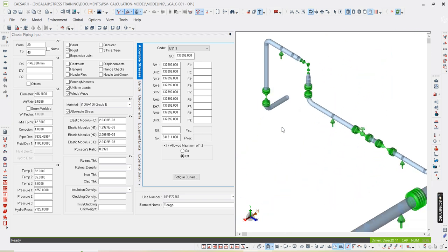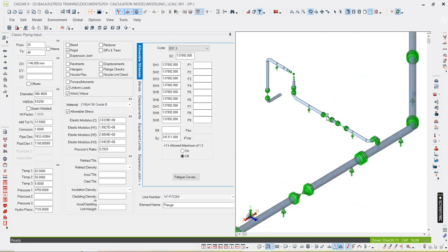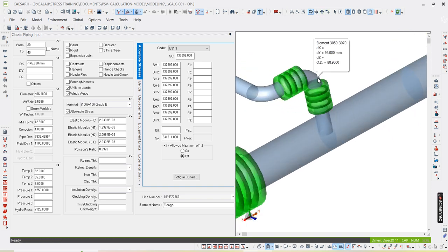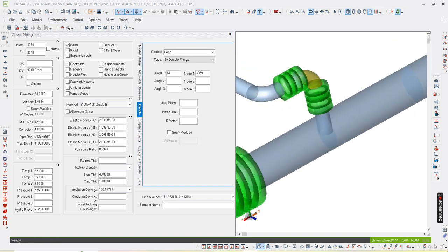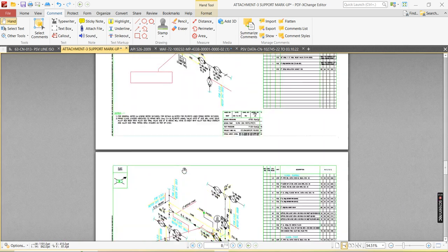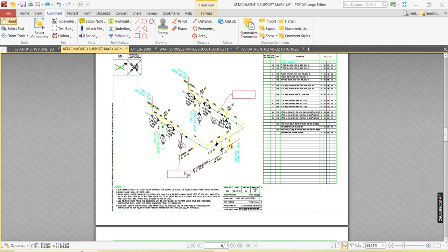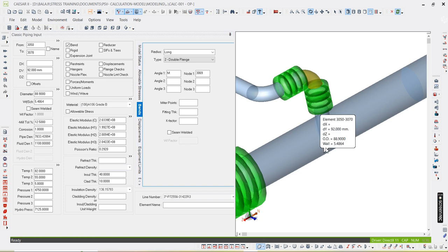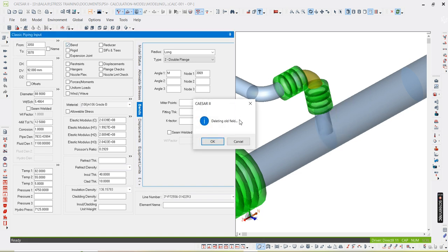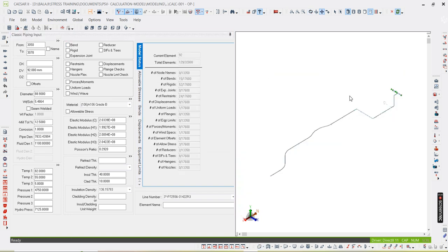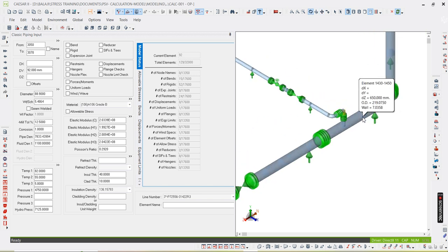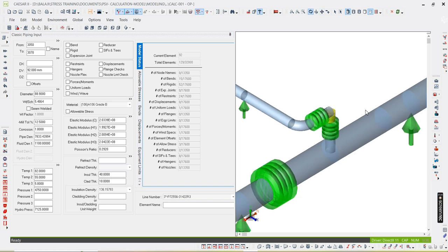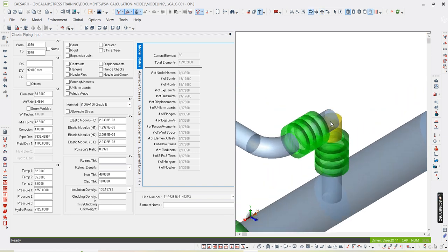So what we are going to do, we will copy this one. Okay, from here. Sorry, here there is no T, I think. So it is not an elbow, it's a T only, no? Yeah, I think it is a T. I have considered it as an elbow. So you delete this. That's why your dimension shows wrongly. Okay. So from here, you select the node number from here.